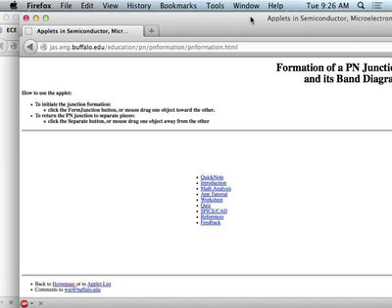But essentially, it simulates the equations that we've talked about, and you can vary the donor concentration and the acceptor concentration, and see how things change. Like how does the depletion region change? How does the field change? How does the potential change, and so on.